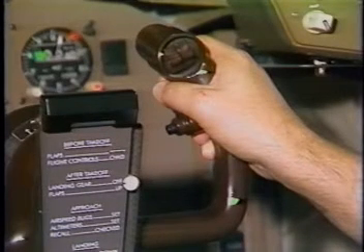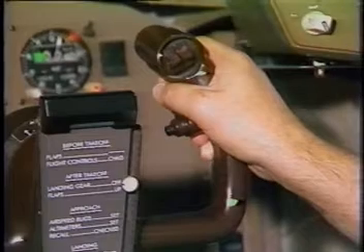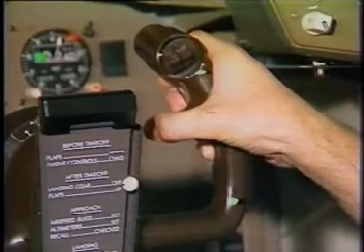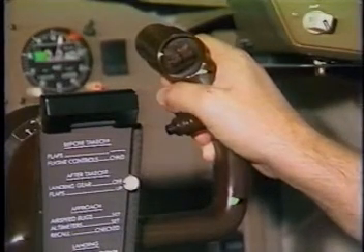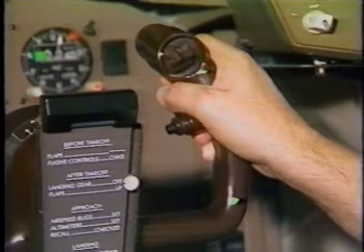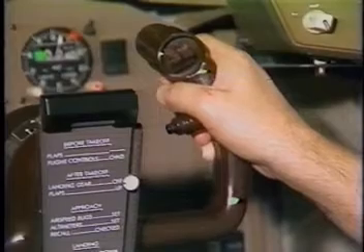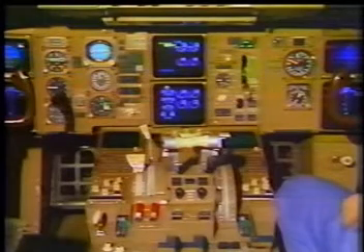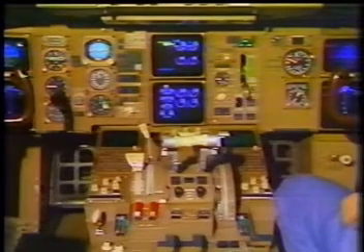The autopilot may be disengaged by pressing the disengage switch on either control wheel. An autopilot warning is activated when this switch is pressed and no autopilot channel is engaged. This permits push to test of the warning function.